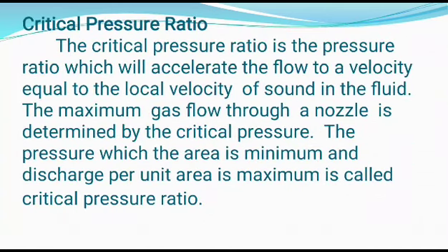Critical pressure ratio. The critical pressure ratio is a pressure ratio which will accelerate the flow to a velocity equal to the local velocity of sound in fluid. The maximum gas flow through a nozzle is determined by the critical pressure. The pressure at which area is minimum and discharge per unit area is maximum is called the critical pressure ratio.